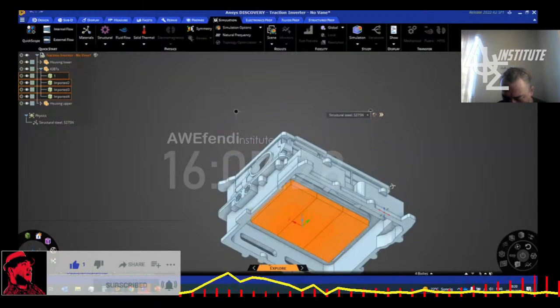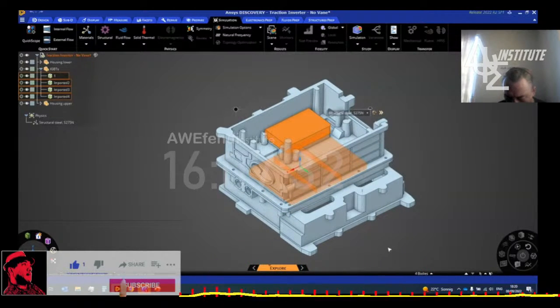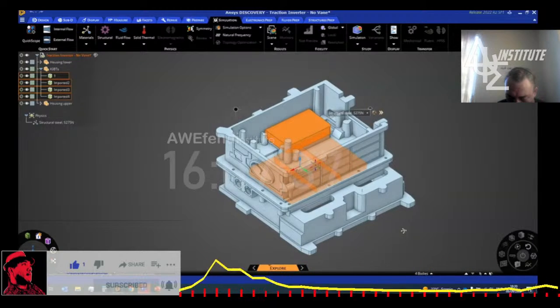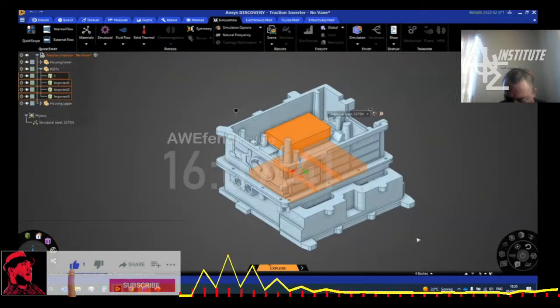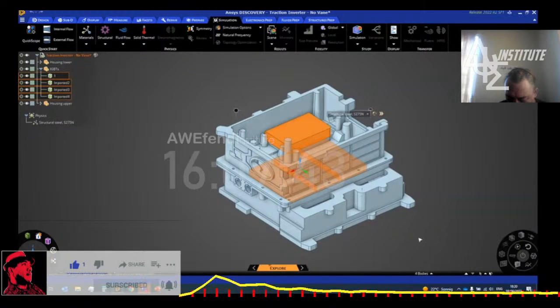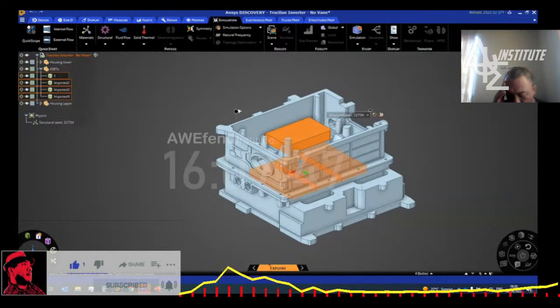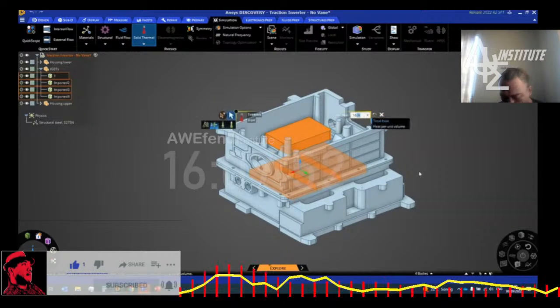So, the amount of complexity and the type of questions that you can ask and answer with ANSYS Discovery are indeed not too advanced in that sense. I mean, here you can just understand pretty much the cooling power that you need, and you can modify the cooling channels a bit to understand which concept looks the best. So heat up a heat source. We can put that at 1,600 watt.